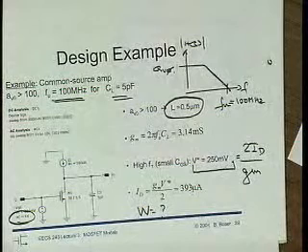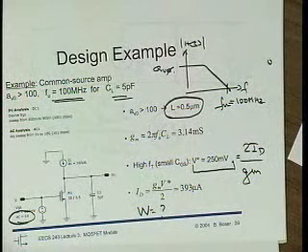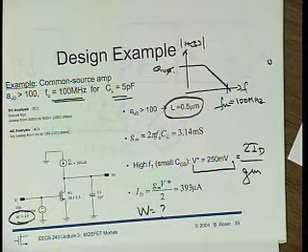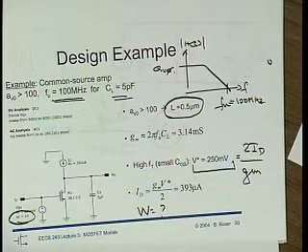Oh, okay. Well, I know that the threshold voltage of my device is give or take 600 millivolts. The V star is not equal to VDSAT, but you know, I add that, then I have roughly an idea of the VGS that I would expect. And so about 800 millivolts, right? And then I sweep around that.